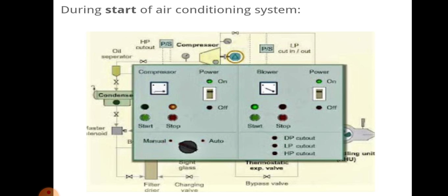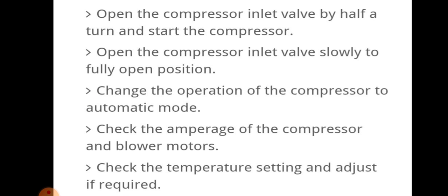During starting of an air conditioning system, what we need to check is, when the air conditioning system is started, we have to open the compressor inlet valve by half a turn and start the compressor. After starting the compressor, we can fully open the compressor inlet valve very slowly.